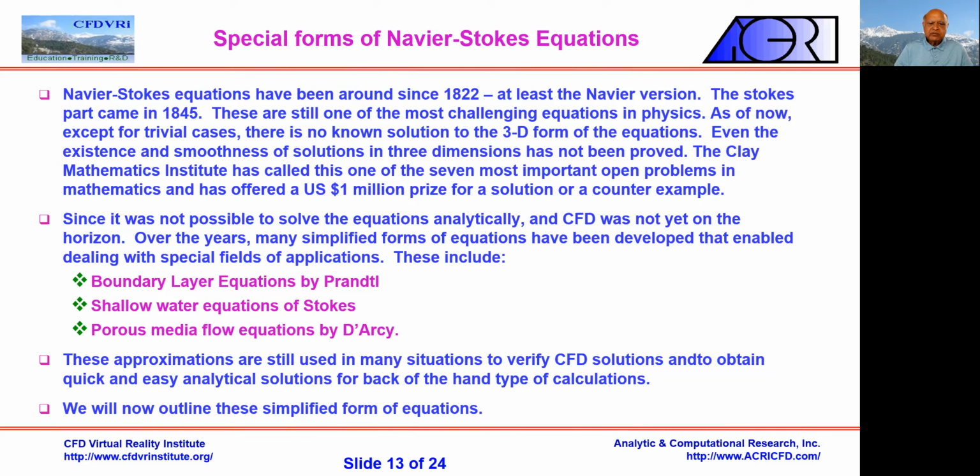Now, since it was not possible to solve these equations analytically, and CFD was not yet on the horizon, over the years, many simplified forms of equations were derived for special applications. I would talk about 3 of them. There's the boundary layer equations of Prandtl, the shallow water equations of Stokes, or sometimes called the long wave equations, and then the porous media flow equation of Darcy. These are practically very important.